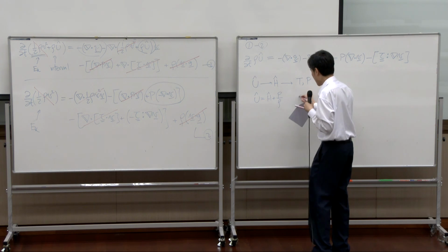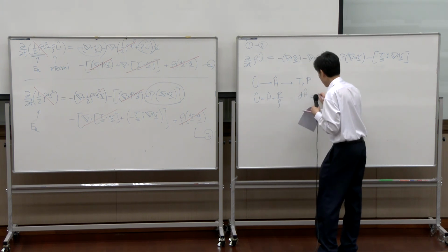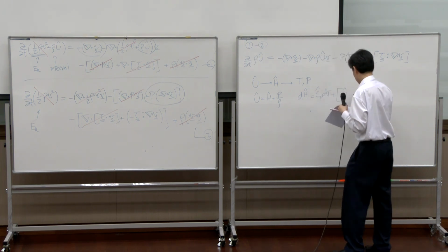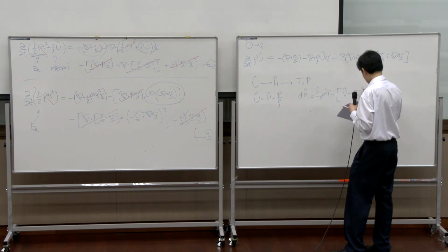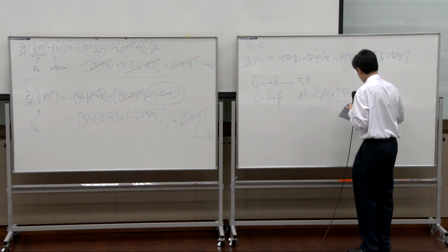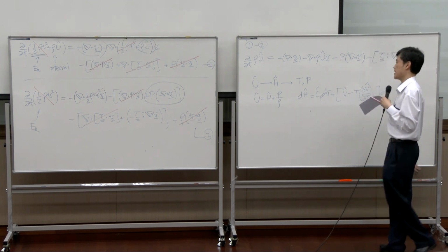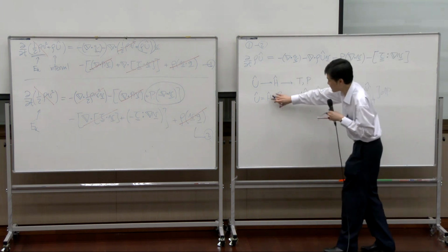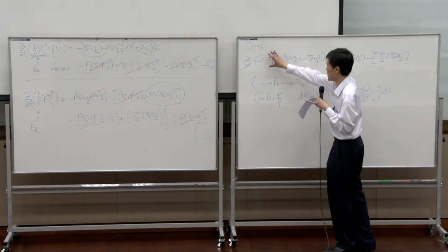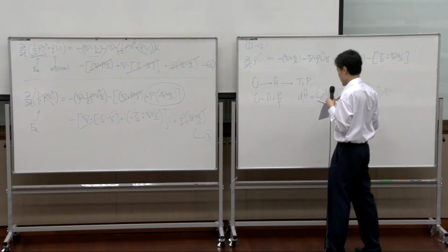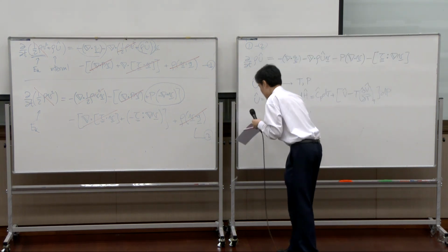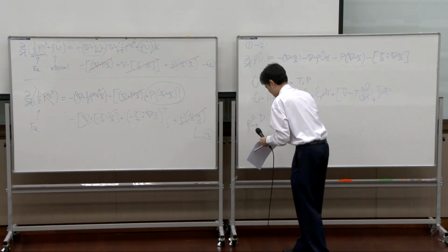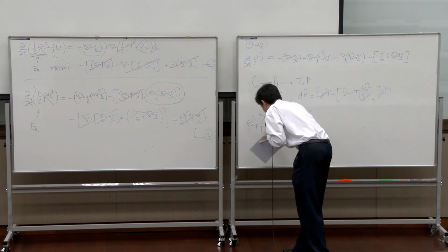And then using thermodynamics, like dH equal to Cp dT plus V minus T dV by dT at constant P dP, and so on. All right? If you plug this into that and plug that into here, you can change this equation into something measurable. On the left-hand side, you end up with rho Cp DT by Dt.